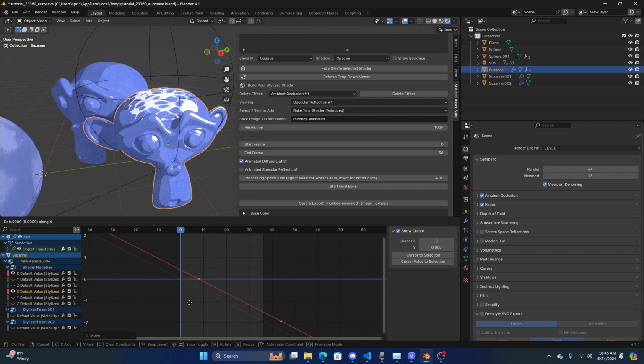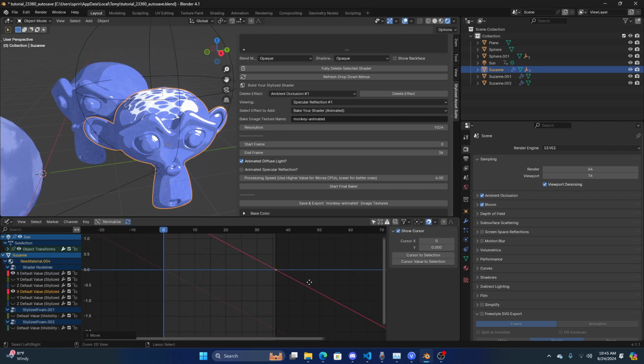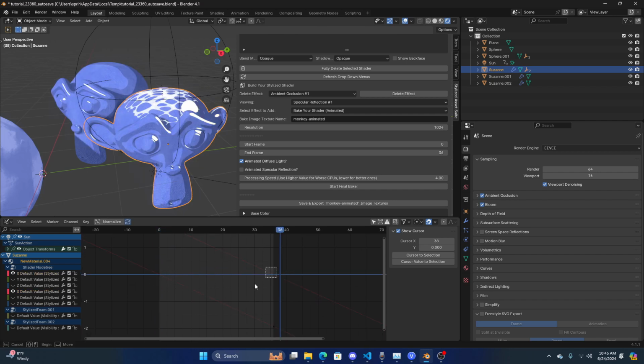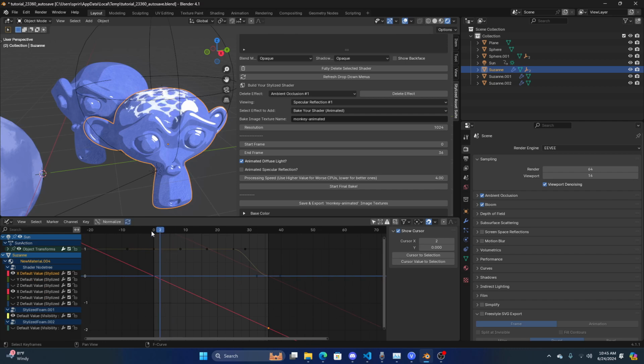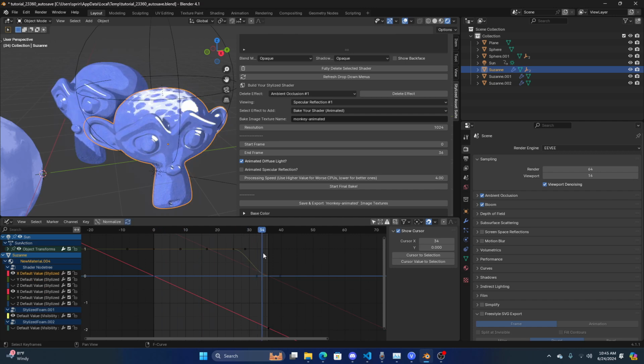So basically you want to move one of the curves so that the first frame is on 36, because then with this we know that this keyframe here and this one here are exactly the same, because these two curves are the same animation, right? They're doing the same exact thing, and so we know that we're starting and ending on the same frame, right? And what we're going to do is while we're here animating and we're using this curve, we're going to have the visibility set so that, as you can see, while this curve is playing, the visibility is set to 1, meaning all of it can be seen. But then once we get to the end of our loop, the visibility goes to 0, so you can't see it anymore.